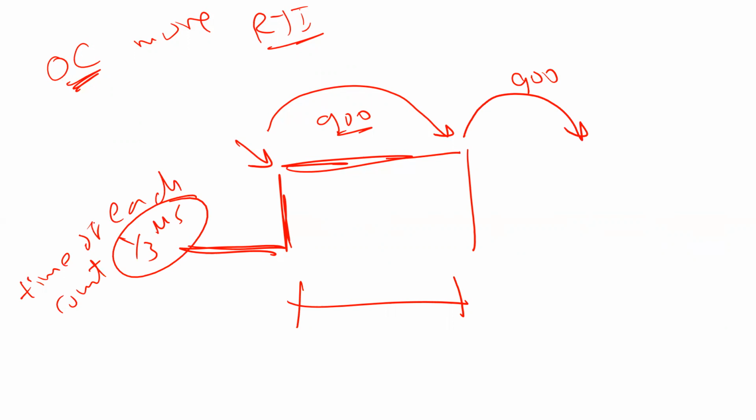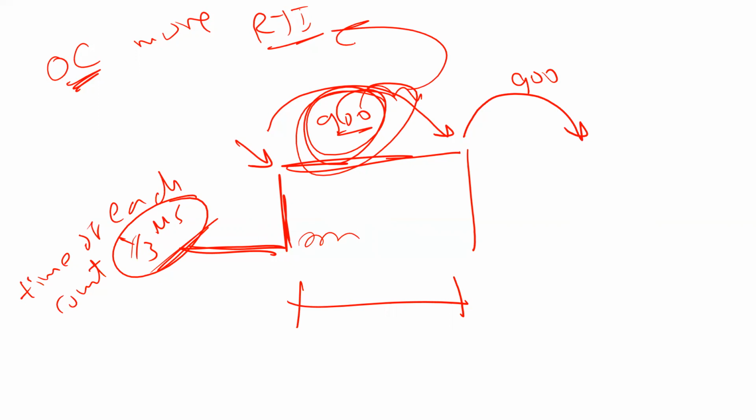If the time of each count is 1/3 microsecond, guys, look how fine grained it is. I can increment this number a little bit, by 1/3 microsecond, right? Very beautiful, fine grained. You can increase it very little. So you can have a very accurate timer, much better than RTI. You got the point here. Every count you add here, you actually increment the time by only 1/3 microsecond. Is that okay?